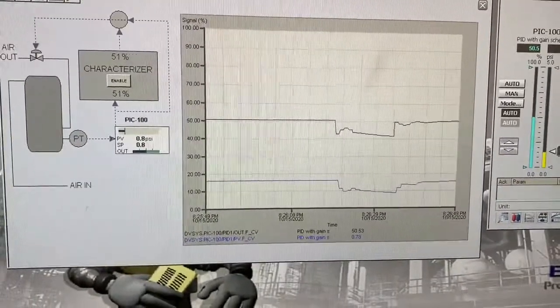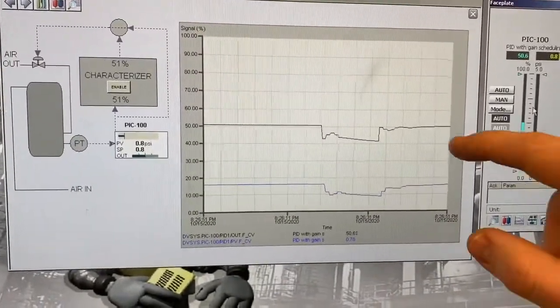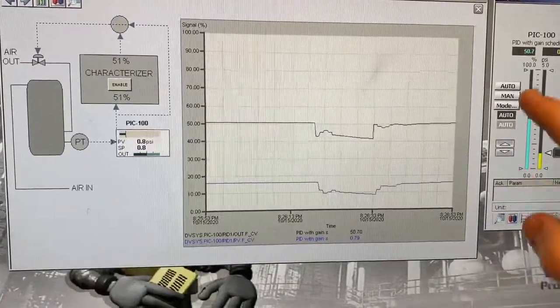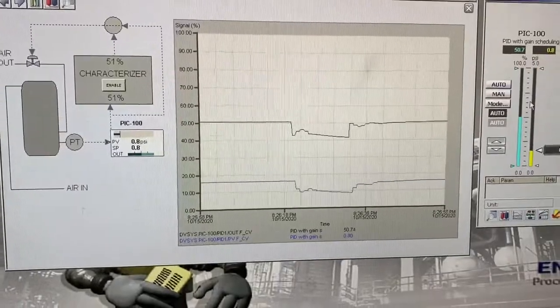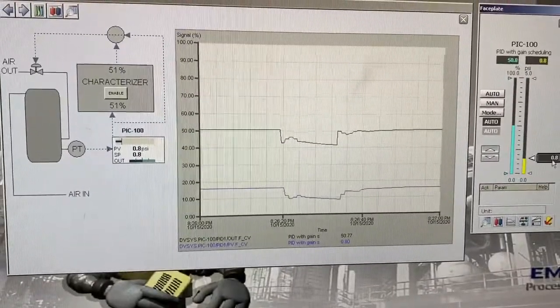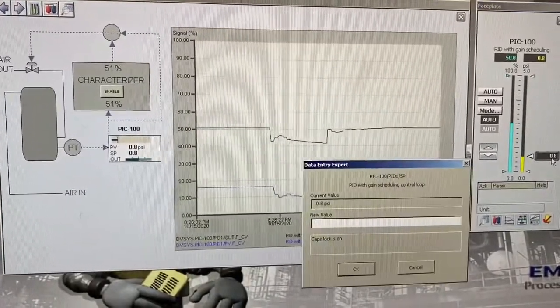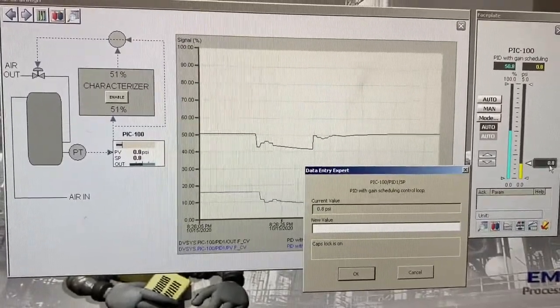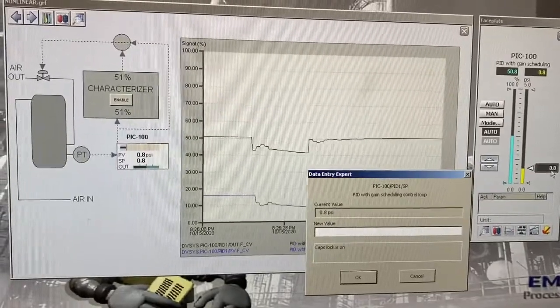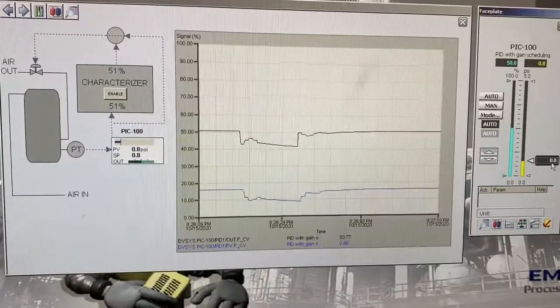But now we said our gain value was quite high when our valve was open around 60, 65, 70%. So let's try to control up in that zone. We'll go up just by small amounts here. We'll go up to 1.5.